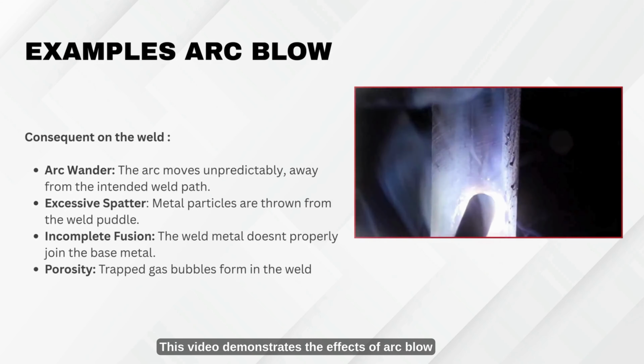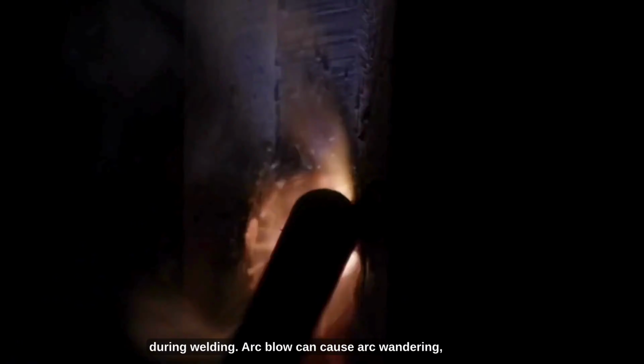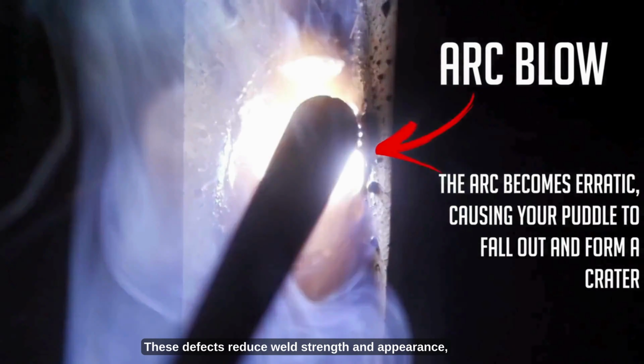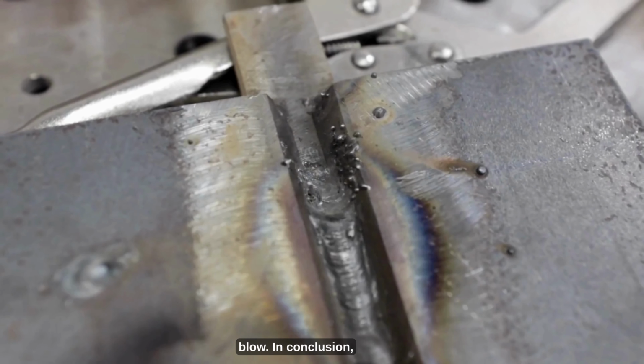This video demonstrates the effects of arc blow during welding. Arc blow can cause arc wandering, excessive spatter, incomplete fusion, and porosity. These defects reduce weld strength and appearance, which is why alternating current is preferred to control arc blow.